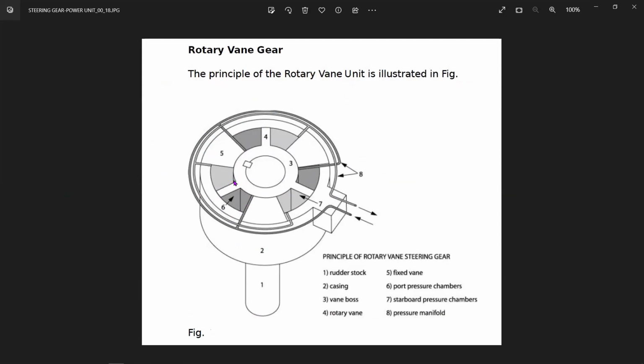And they are saying it is only possible 35 degrees one side to 35 degrees the other side. So from 110, take out 70 degrees. That leaves 40 degrees. So this 40 degrees means 20 degrees is the stator thickness over here. So if I want to draw it, just give me a second.